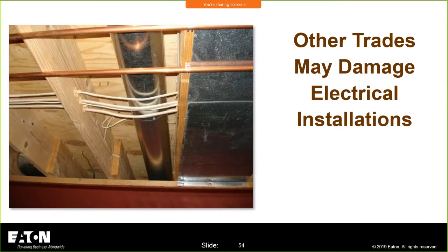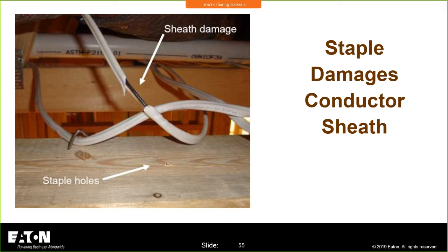And so the picture that you see here is one of those areas where, after he left, the HVAC guy came in and he says, "Well, these wires are in my way." So what does he do? He had a little broom handle, and he would put it up behind all those wires, and he would yank them down and then push his ductwork behind those wires. And I didn't see him doing it. I saw the broom handle, or it was a cut off broom handle, and I sort of put 2 and 2 together. He could have jeopardized those conductors. He's running it through ductwork, through the return path, and there's probably lots of different things that were wrong in that installation.